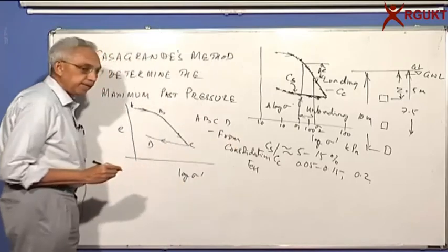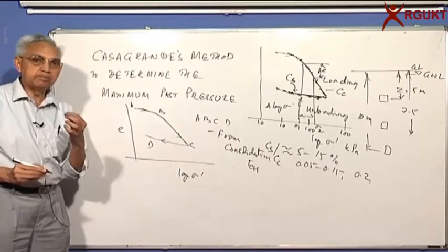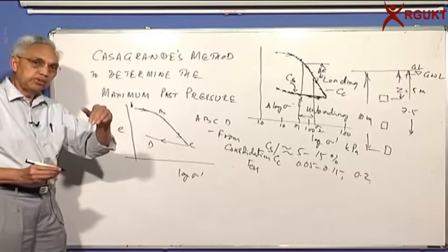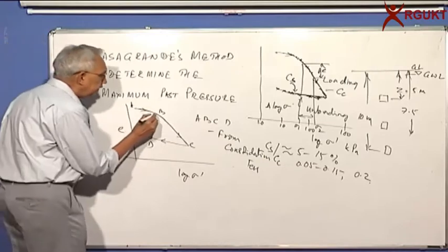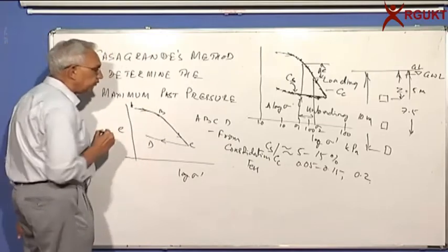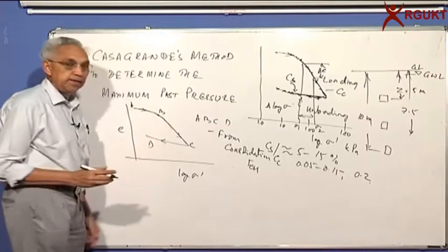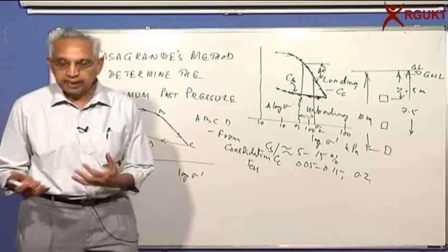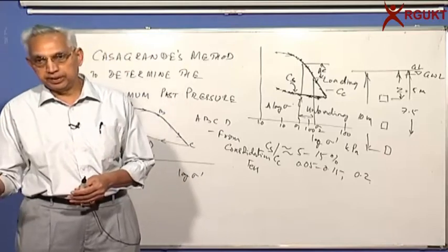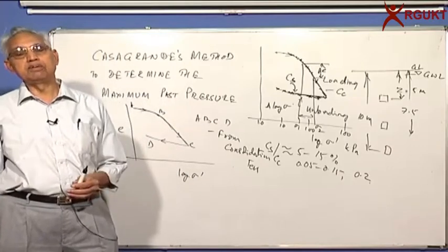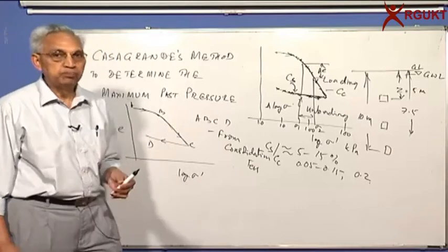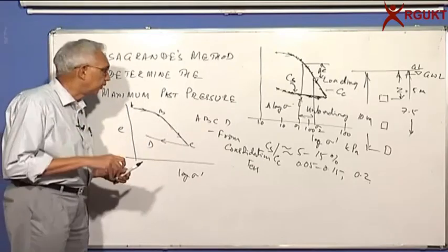He said pick up the point of maximum curvature, which means the shortest radius. So if I look at it here, I can get somewhere here. You can see this is flatter, this is also flat. A straight line has a radius of curvature of infinity, which means the curvature is very, very low, whereas a circle will have the smallest radius.